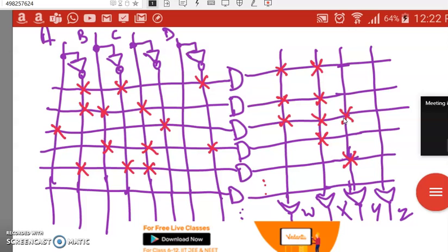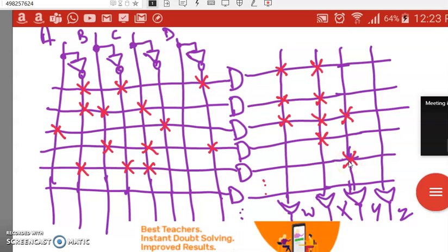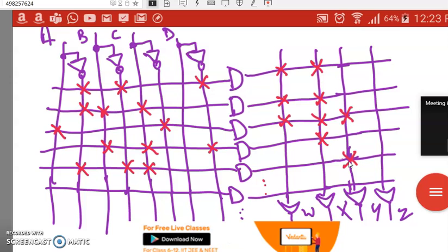In the same problem we discussed in the last class, this AC bar we connect with the same line. This is how you can do it. Otherwise, you can have one more AC bar implementation and do it that way, so there will be less confusion. So here you need to be careful about how to connect in the PLA. The program tables are different in both of these, because here you create the table with respect to the product terms, and there you create the table with respect to each expression.